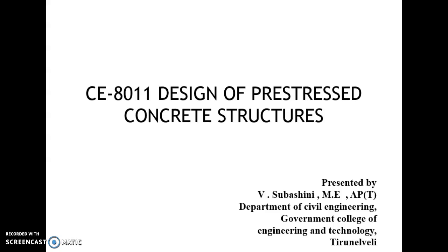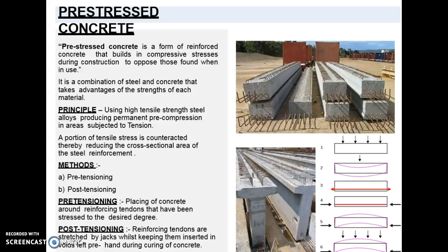Welcome all. In today's presentation, we are going to see about the introduction of prestressed concrete structures. Prestressed concrete is basically a concrete in which internal stresses of a suitable magnitude are introduced so that the stresses resulting from the external loads are counteracted to the desired degree.